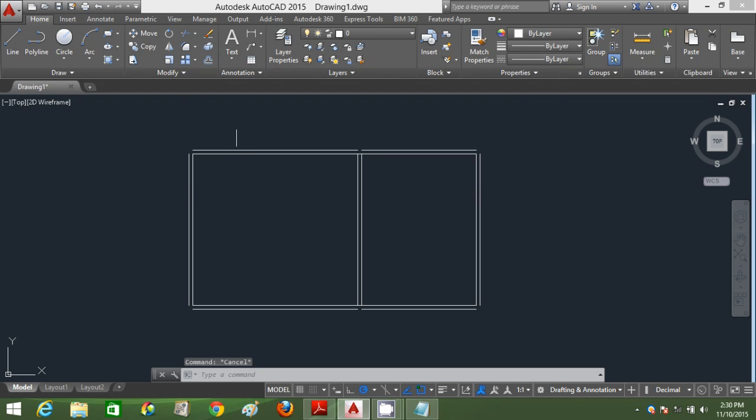And I'm going to use fillet now to join all the unjoined lines. Click fillet and click this line, click the other line to join it. Alright, so I'm just going to use the line command to extend this too in order to close that loop.